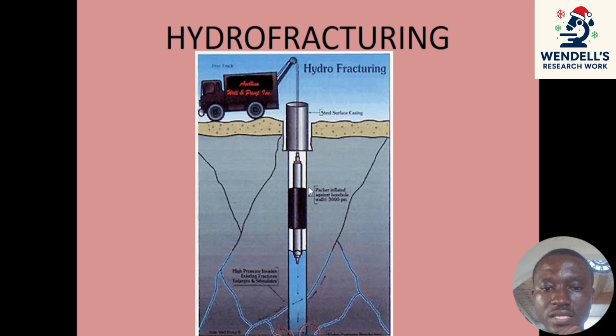So you can use pumps. But if the yield is not that high, you may use hand pumps and all that. Boreholes are amenable to quantitative monitoring and testing, which enables accurate assessment. Like the pumping test, when you do it, we are able to assess it, and then the water is supplied sufficiently, and then we are able to design the storage and the distribution system.